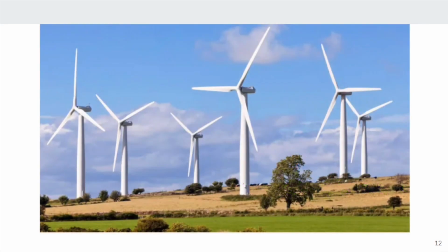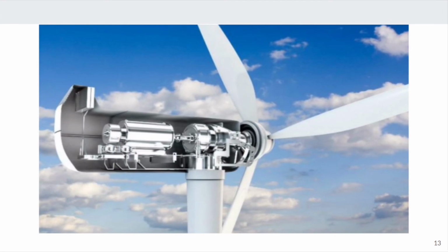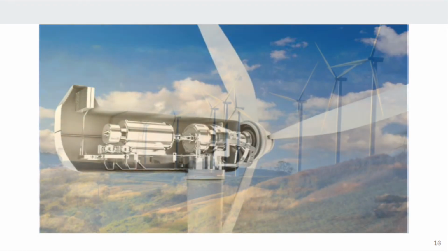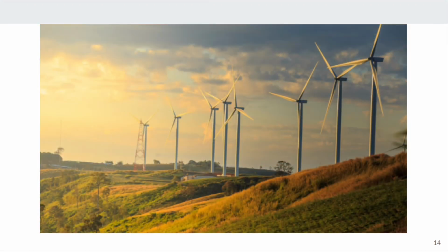In summary, for the blade, due to the sharp connection, the overall FOS is lower. You still need to change the material composition and the structure before it could be used in production. About the generator, the center temperature is still high, which is mostly due to the design and boundary condition setup. At last, for the tower and base, the simulation shows great promise for the structure robustness, so the design is good.